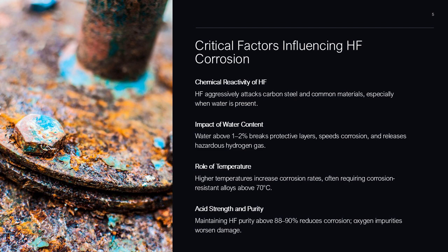Even small amounts above 1 to 2% can disrupt the protective iron fluoride layer, accelerating corrosion and releasing hydrogen gas, which introduces explosion hazards. Temperature also plays a major role, with corrosion rates increasing at elevated temperatures, often requiring a switch to high-nickel alloys like Monel for service above 70 degrees Celsius. Acid strength is another key parameter.